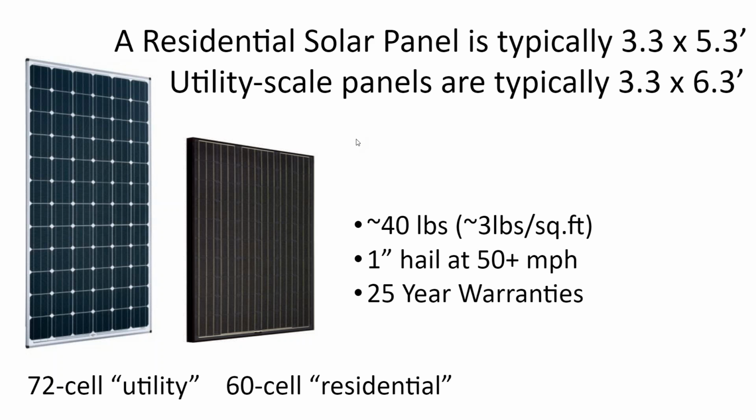Solar modules are so strong that they give the installer a false impression of strength. You lay a solar panel up on its side against the side of the house while you're staging it, a gust of wind blows it over and it smacks onto the ground, and you'll shatter the glass. The installer might be surprised because he's used to just throwing the solar panel in the back of the truck and driving down the road and it being just fine.